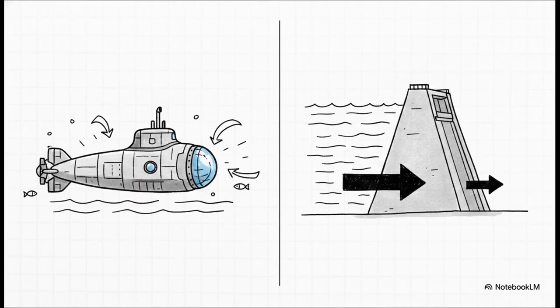This is where human ingenuity really shines. At 600 meters down, marine exploring vehicles are facing pressure that's 61 times greater than at the surface. That is massive. To survive that, engineers design submarines with these thick, curved, spherical hulls because those shapes distribute that crushing force incredibly well. Their viewing windows are made of solid acrylic plastic, nearly 10 centimeters thick.